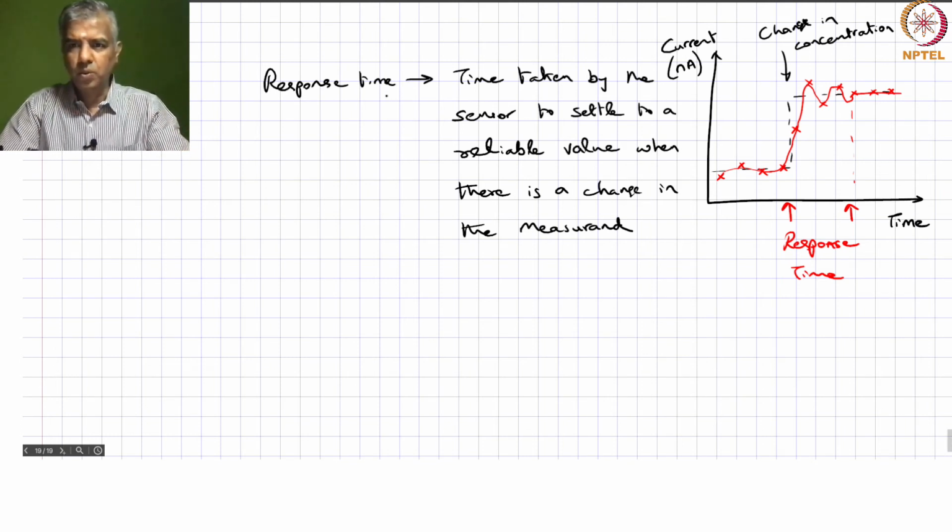And of course you typically want a fast response time, which means, what actually controls response time? Well, the receiver bandwidth is probably one of the most important things, that will limit the response time in a fundamental manner. So you need to have as quick a response as possible, which means we need as high a bandwidth as possible as far as your receiver is concerned. So the receiver bandwidth has to be very high.